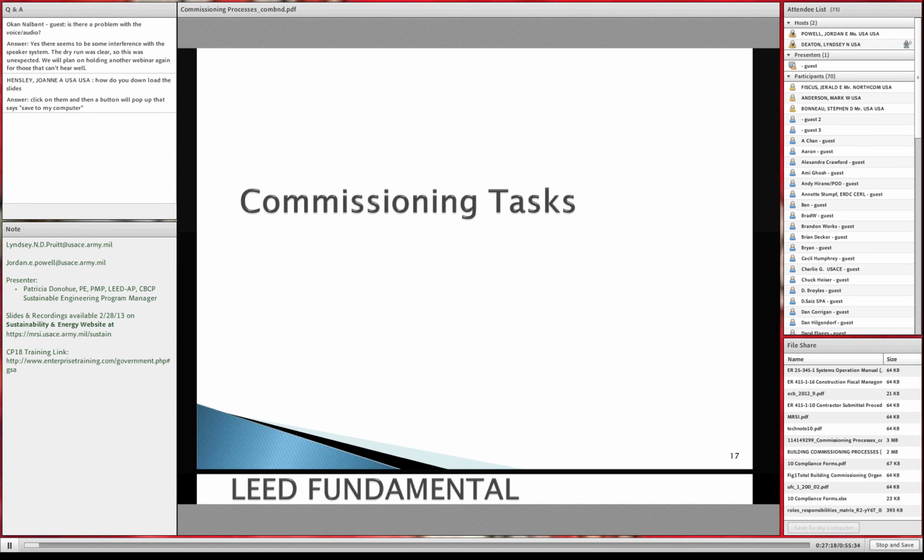Yes, and LEED has that checklist, and it's almost like you should be at least following the LEED fundamental. You have to follow LEED fundamental, and you should probably be following LEED enhanced commissioning. But we keep getting wrapped around the axle on the third-party reviewer commissioning authority. So that's kind of why we're trying to take the narrative back a step and say, what are we really trying to do here? Are we trying to satisfy a point in LEED, or are we really trying to turn over a building that operates properly?